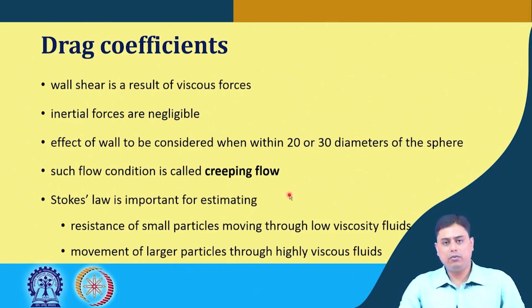Otherwise, we can say it is an infinite pool with respect to the particle diameter d. If the walls are separated by more than 30 d or 20 d, we can say it is an infinite pool of liquid with respect to that particle, and Stokes' law is typically applicable. If not, the effect of the wall has to be considered, and certain modifications need to be made in Stokes' law to calculate the drag force on the particle.